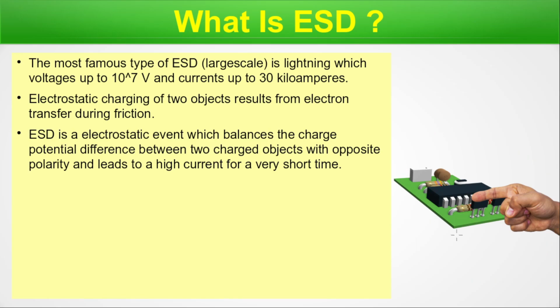So those electronic engineers who do this kind of assembling and handling of these circuits use an electrostatic strap that they tie to their hand and which is connected to the ground, and maybe in both hands they have 2 different ESD straps, so that the human body is electrostatically protected, so that touching any device will not damage it. So such kinds of electrostatic straps are used in the electronic industry where electronic circuits are packaged and assembled. This is just for your knowledge.